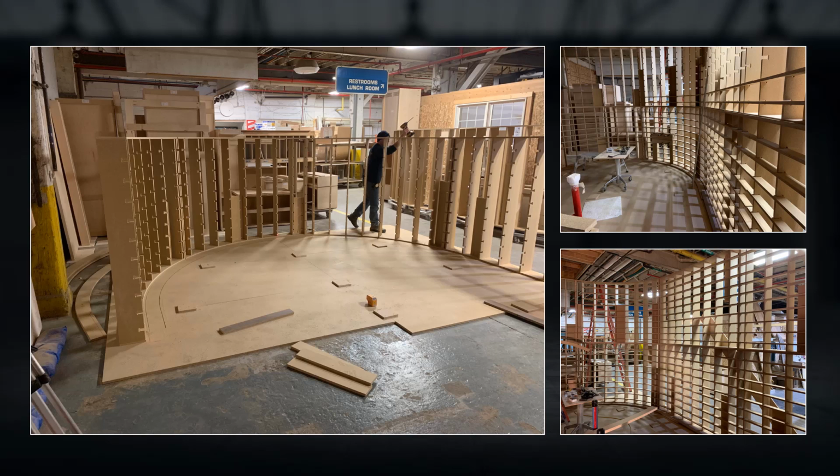And then, in order to take out the variables, since the walls are never actually a true radius or perfectly plumb, I built our room a 1/2 inch smaller all the way around, so 1 inch overall, and built in a 1/2 inch of shim space. All the panels were finished edges with 1/8 inch space between them because they wanted it to look like the cabinet doors, which were just full overlay frameless boxes.